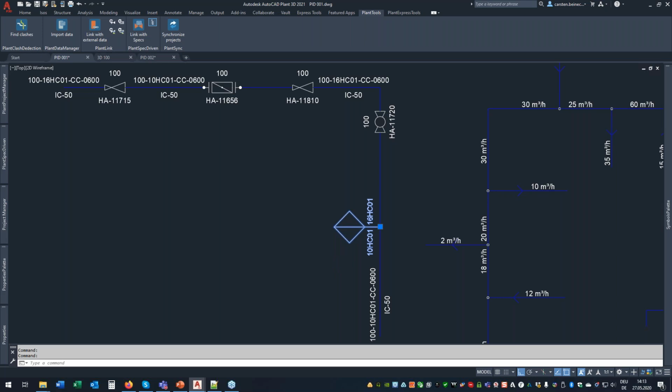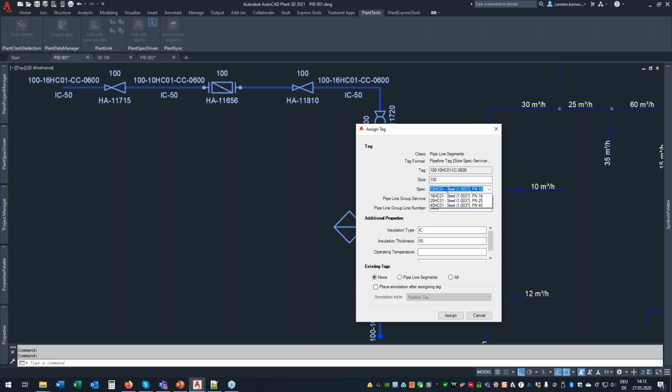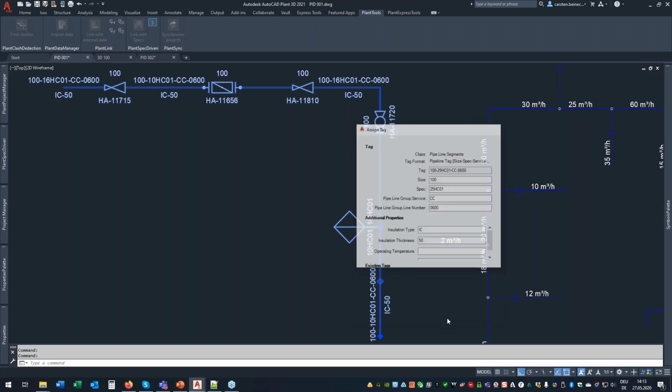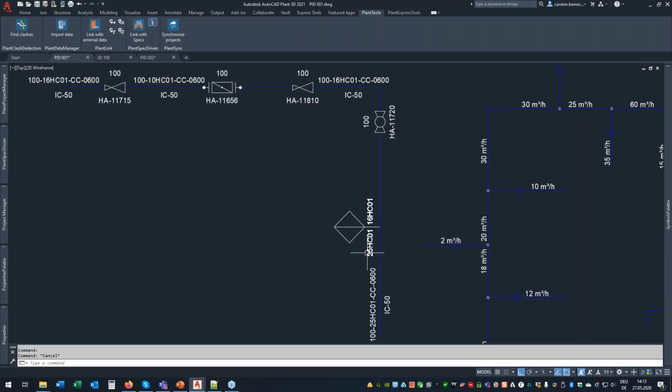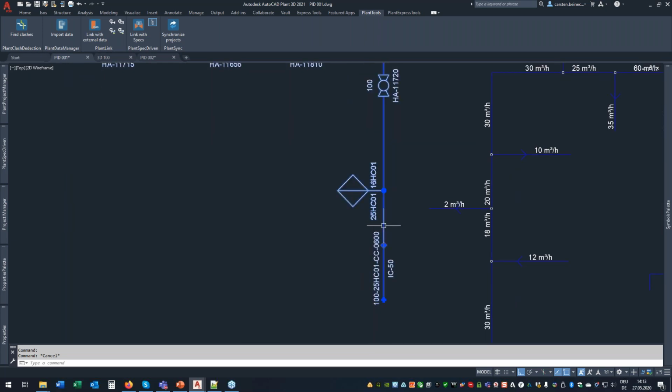And let me just check. That's okay. No, there's something wrong. I did not prepare this. That should actually be a different pipe spec. Okay. So obviously the pipe spec, if I change that, doesn't flow over the spec break symbol. Otherwise, I would have the same spec break every time. So now let me delete this. That's strange. That was not a...